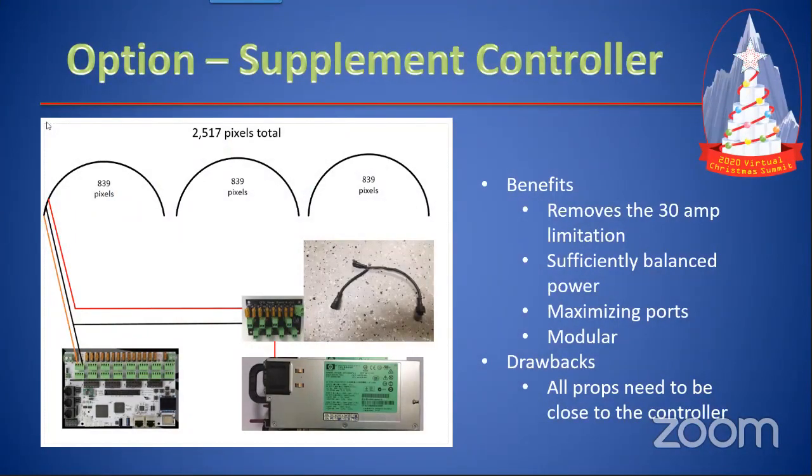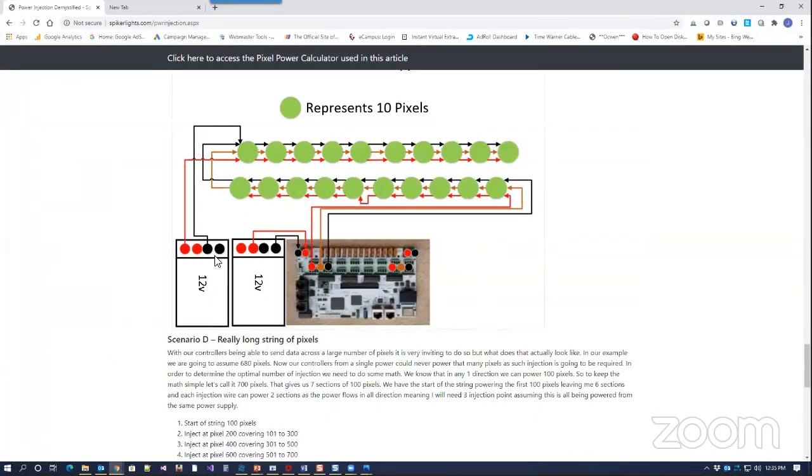And let me share. I'll give you an example of multiple power supplies. Hold on. So here, in this example, it's sending power and data off the controller, and then I want to inject from a separate power supply, so the V plus is cut right here and then reinserted over there. That way you ensure that you never cross the V plus, but you'll notice the grounds are still tied together. You always want the grounds tied together.